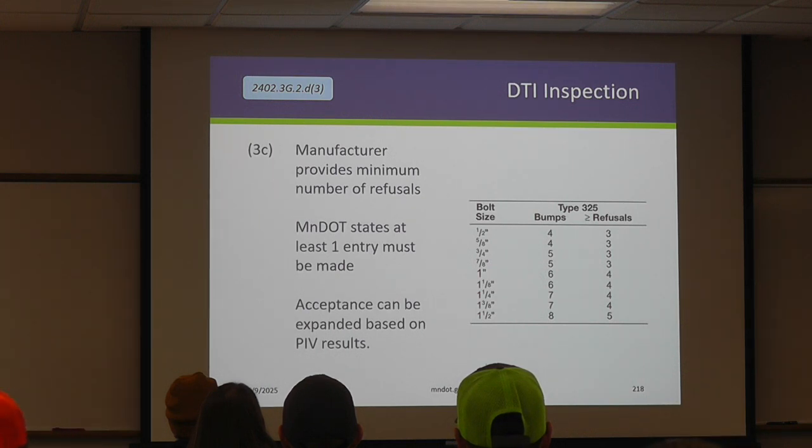That's why it's really important that you're observing the contractor, because I wasn't there for them to say, yeah, these last 600, that's exactly how we did it. Right? I'm taking their word at that point. But they demonstrated to me that these are being that finicky. So we compromised by picking about 10% of the bolts in the connection and redoing them using that same procedure to verify. That's a lot of work, right? That was about 2 hours worth of effort. So these things can be really finicky.